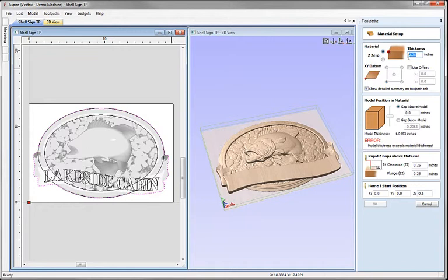So I'm going to enter a material thickness of 1.5 inches, Z0 off the top of the block still, XY datum lower left, and then I'm going to add a small gap above here, so round about 0.05, 0.6 of an inch, just to give us a little bit of space above the job to allow for any inconsistencies in our material and how flat our material is.